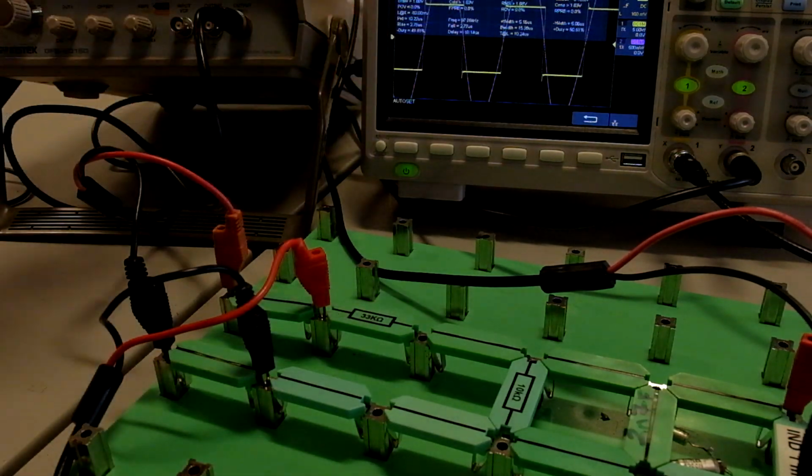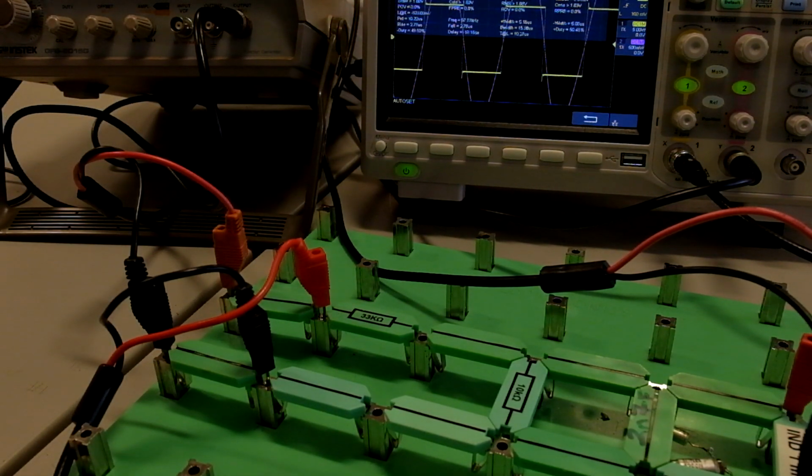A square wave from the function generator is made up of adding sine waves together of different amplitudes and different frequencies. For a square wave, we add odd harmonics. So we've got a base frequency, and we've got other harmonic frequencies, 3 times the base, 5 times the base, 7 times the base, and so on. Higher frequencies make that up. What this circuit does, because it's a bandpass filter, is only pass the signal through in a narrow band centered around 97 kilohertz.